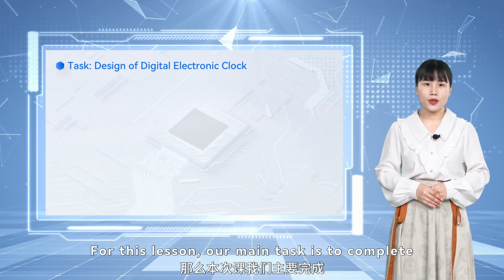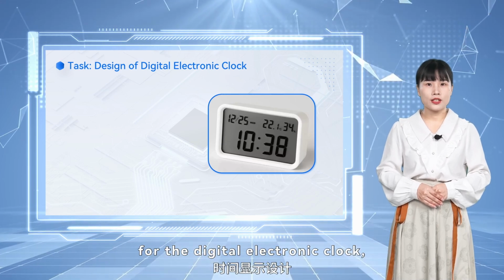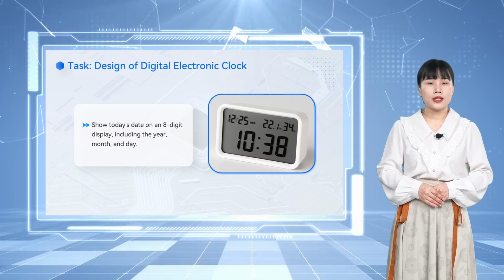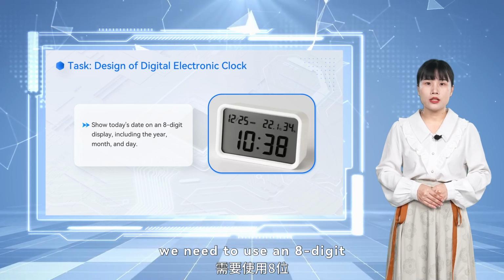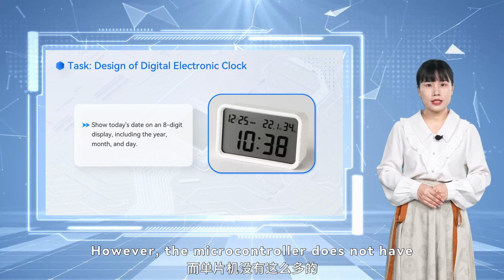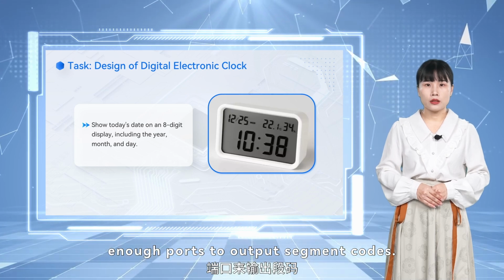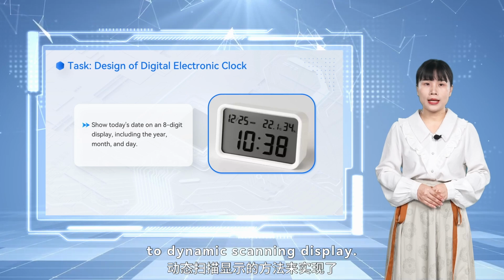For this lesson, our main task is to complete the design of the time display for the digital electronic clock, which involves showing today's date on an 8-digit display. To display the year, month, and day simultaneously, we need to use an 8-digit or even more digit displays, as a single display can no longer meet our needs. However, the microcontroller does not have enough ports to output segment codes. Therefore, we need to resort to dynamic scanning display.